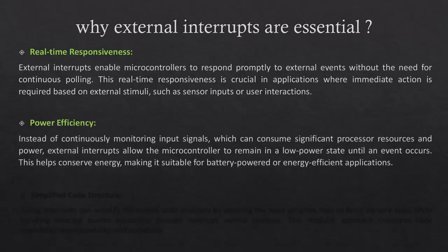Power efficiency. Instead of continuously monitoring input signals, which can consume significant processor resources and power, external interrupts allow the microcontroller to remain in a low-power state until an event occurs. This helps conserve energy, making it suitable for battery-powered or energy-efficient applications.